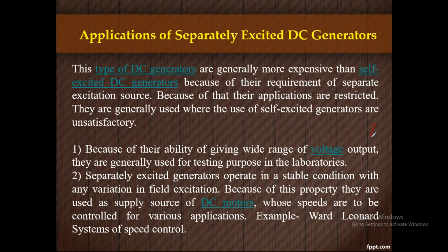So here one motor is there, and this is the motor we have to control. How we can control it means by using the generator here. In this generator the field is separate, okay. So based on the speed, suppose we want 15 RPM, the excitation is increased. When the excitation is increased, EMF will be increased. That EMF will be delivered as the electrical input to the motor, okay. So for example, to get 15 RPM we need 230 volts, and this 230 volts is given as input due to the excitation.